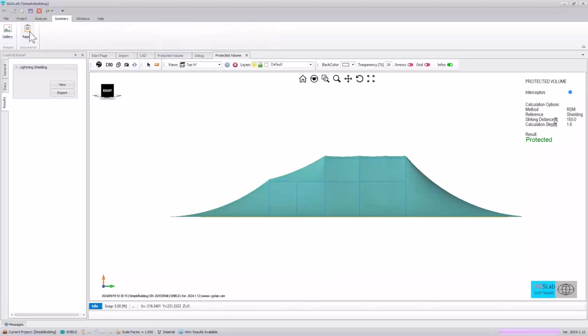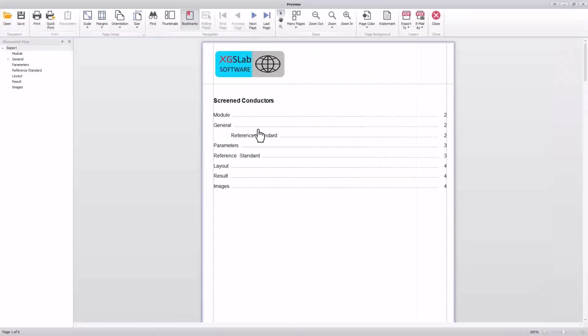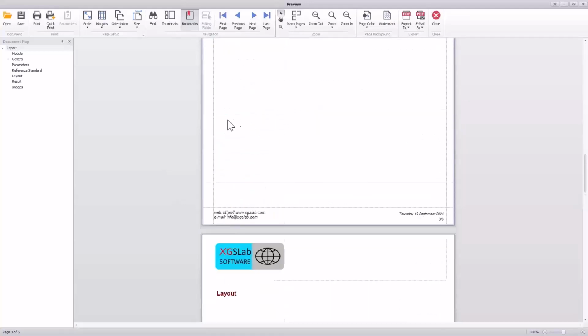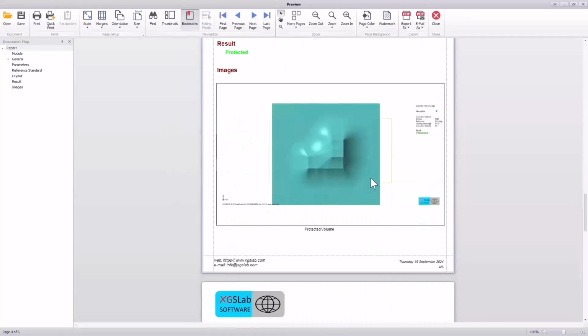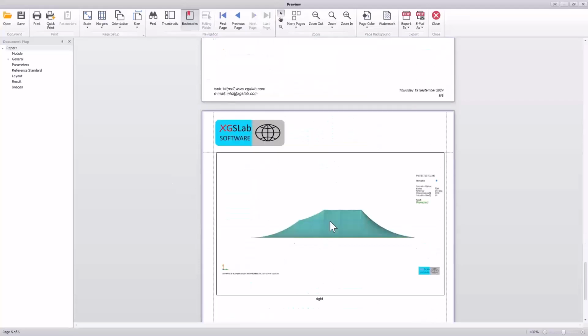And of course, we need to create some sort of report to illustrate that. So here would be just the quick, simple version: we have a shielding system and a lightning protection system, and our striking distance is following the NFPA 780 with a 150-meter sphere or striking distance, and our protected zones as illustrated here.